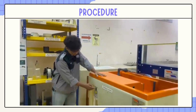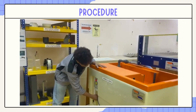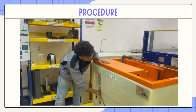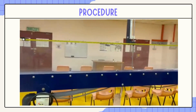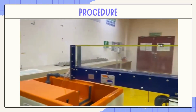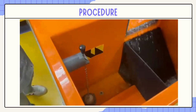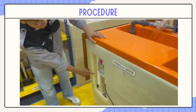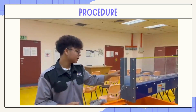So next we turn on the hydraulic bench and then open the valve to control the flow rate. The dump valve, so the water tank is filled. And then we measure the flow rate by fixing the volume and set height. The next step is we put the gate to create the hydraulic jump.